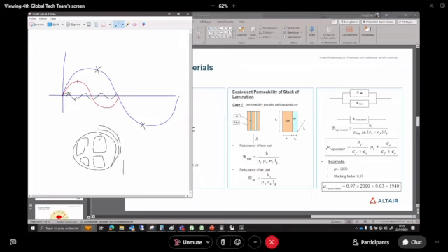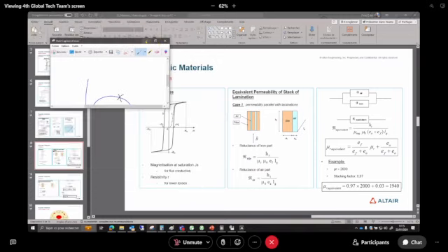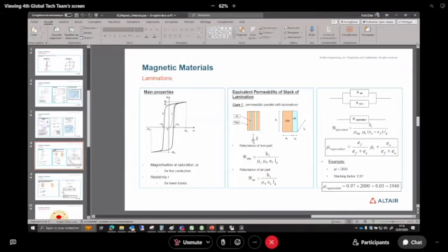So finally, the magnetic field B is parallel to the lamination, right? So the laminations are parallel to B, and here, as you can see, between each lamination there is insulation. We can consider it as air. Why is there insulation? To avoid that the current goes through from one lamination to the other one.